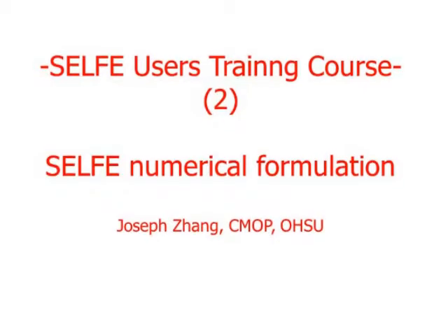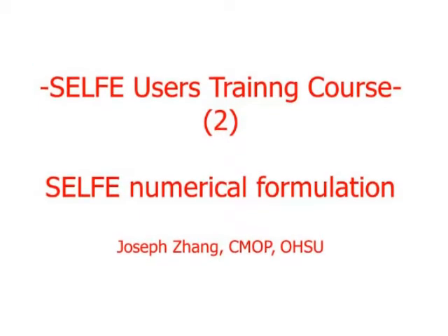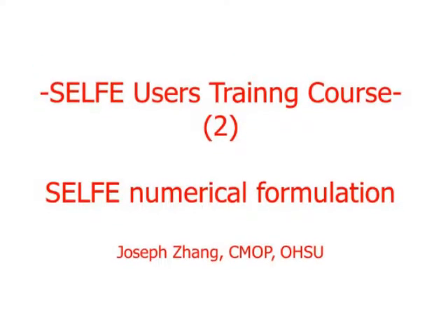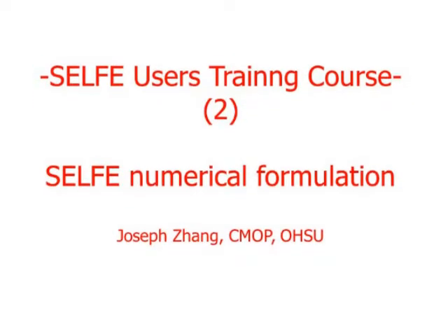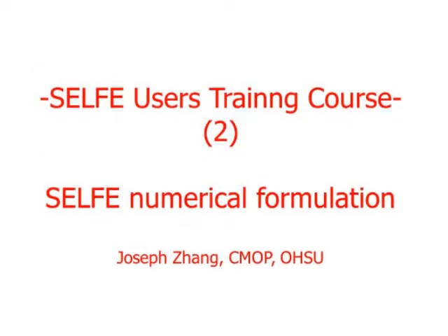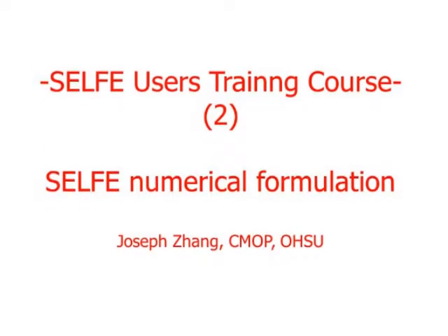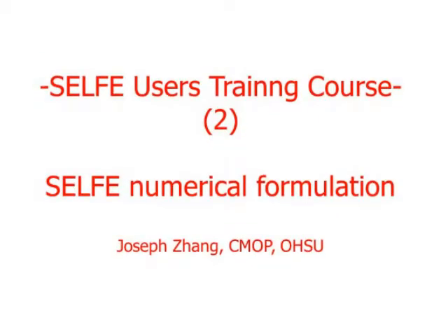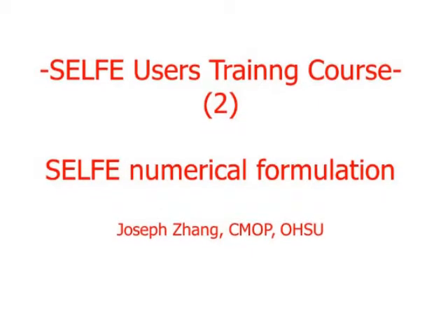The capital letters are typically used to denote depth integrated quantities. So capital U is the total depth integrated velocity, and phi i are the shape functions, which are the same as the weighting functions because we are using Galerkin methods. Theta again is the implicit factor.